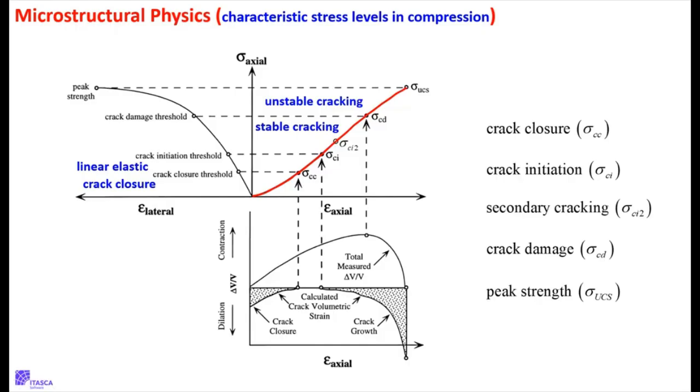You start to get interfaces between the grains starting to break. And then you continue to load it, and a few of the grains actually start splitting. And of course, when you squeeze a grain, it splits, and the crack forms parallel to compression. So it splits apart, which gives you, again, more expansion, more change of this.